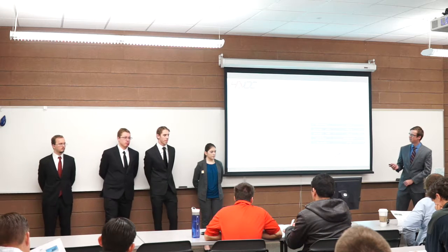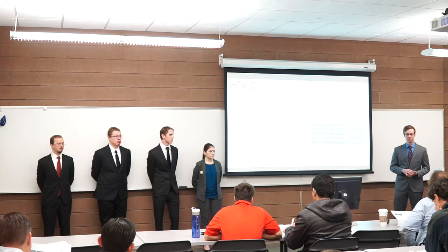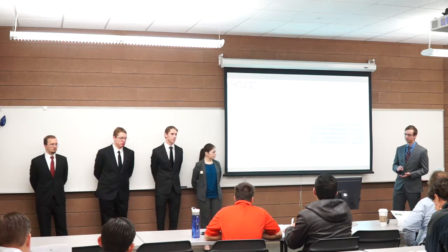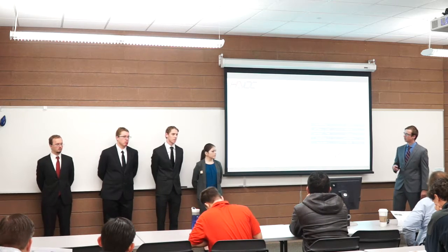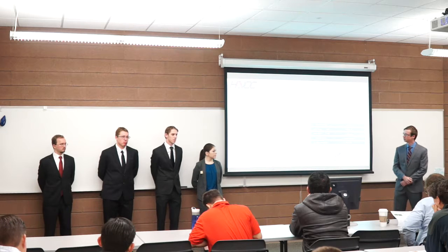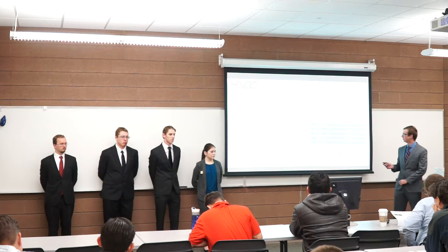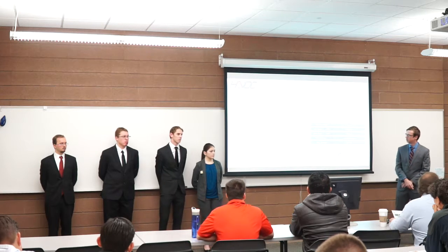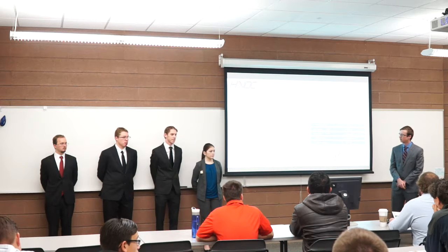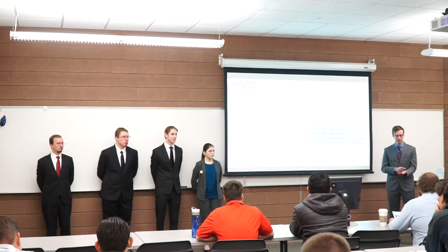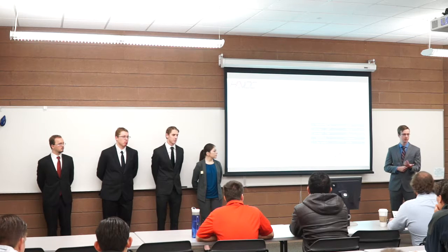We need to find the total force that each finger needs to apply from our specification of a 10-pound weight that the hand must hold. And this comes out to about 11 newtons per finger. The servo torque we can estimate to be about half of the stall torque, which is about 1.7 kilograms of force per centimeter. We've also made calculations to determine that we need about 3.5 centimeters of travel to actuate the fingers.